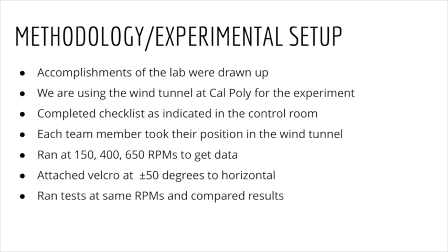The wind tunnel is a large structure that has three main areas inside of it. The first being an inlet that pulls in the air. A 10 centimeter thick honeycomb air filter maintains a laminar flow. After that, there is a test section where the parts and models are placed for analysis. This is where our cylinder was placed.